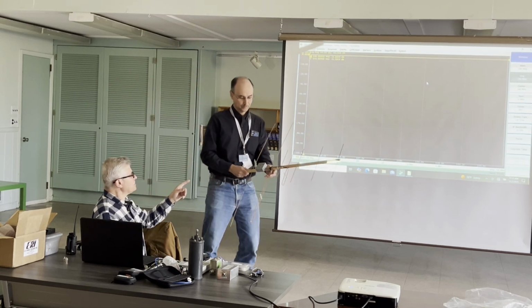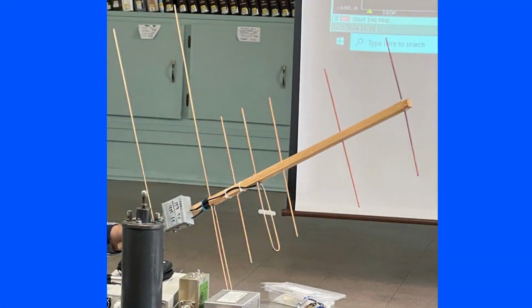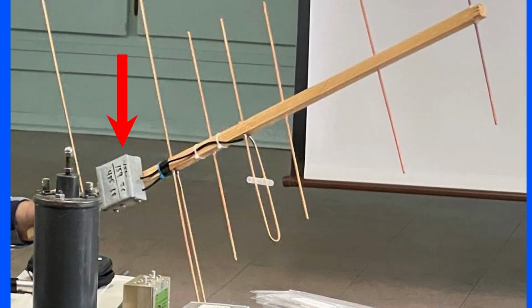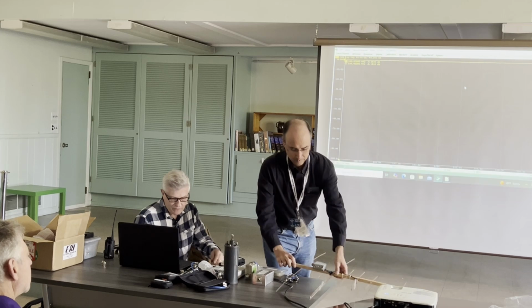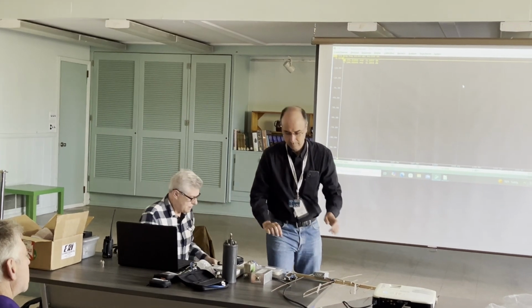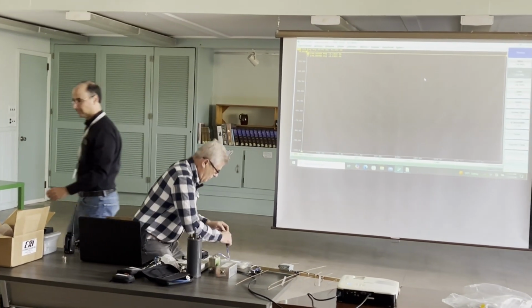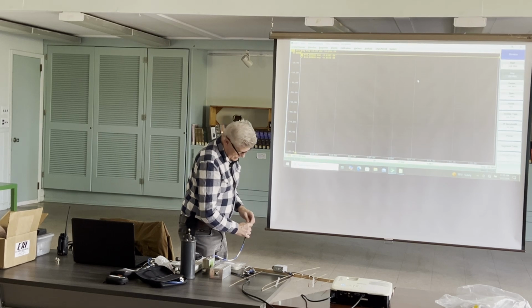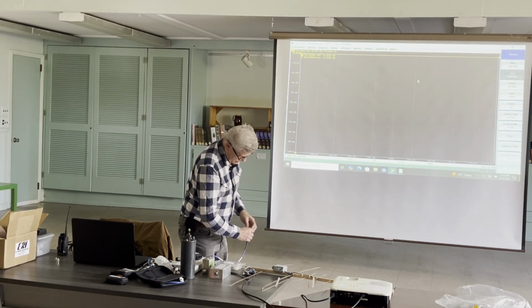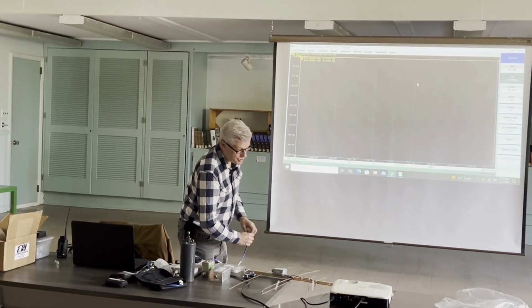So Lou made this. This is a two-band Yagi, right? VHF and UHF, and then you made your own duplexer. Right. And I have these schematic. Okay, so what we want to do is find my SO239 adapter. Now, understand that this is probably going to be impacted by the surroundings here, because this is a directional antenna.